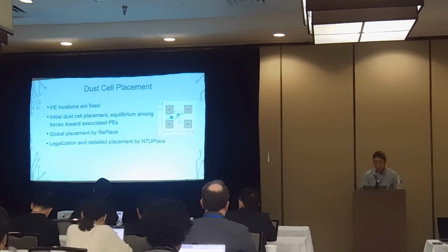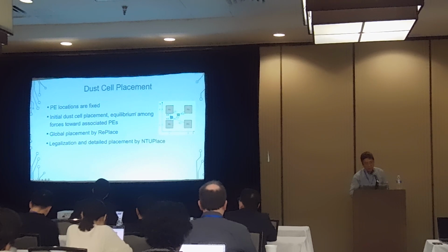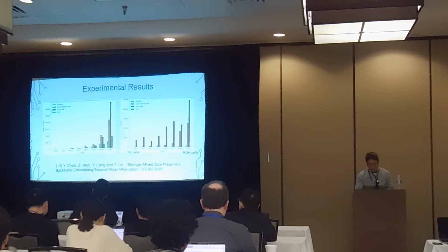Okay. And after that, we fix the locations of the PEs, and then we release all those standard cells to replace them. For those standard cells, first we have an initial placement according to the force balance by the nets through those PEs, and then we run RePlAce, and the final legalization and detail placement is through NTUplace.